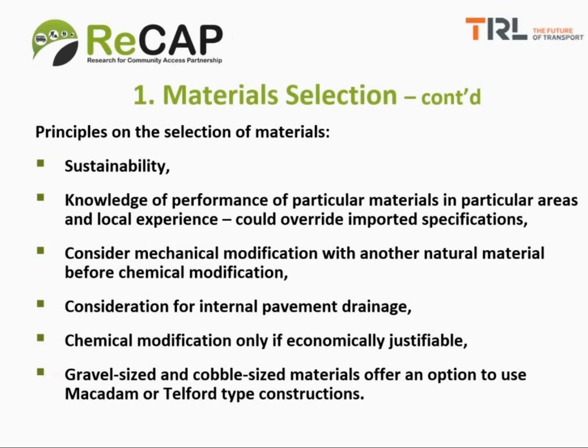And the fifth principle is that chemical modification should only be used if it can be shown to be economically justifiable. And lastly, you should be aware that gravel size and cobble size materials offer an option to use construction types such as macadam or Telford constructions, so they should not be unnecessarily discarded.